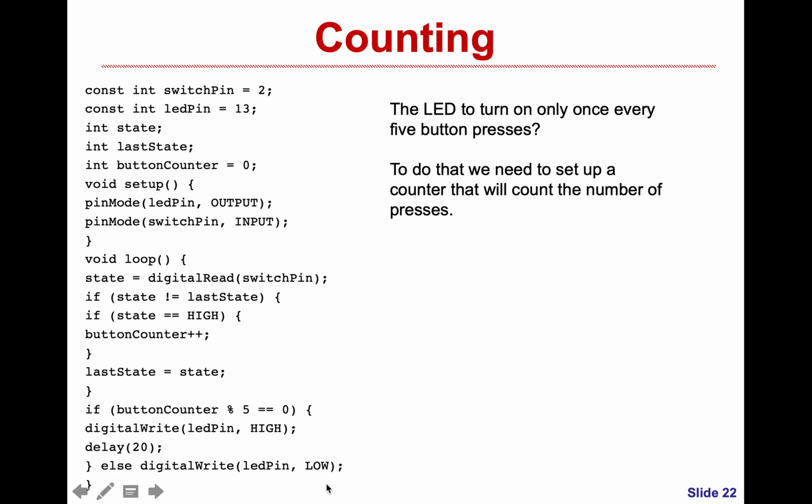So in this way, we will finish the digital input-output. Today in this lecture, we have covered the 14 digital input-output pins of the Arduino and the 6 analog inputs that can be used as digital inputs. We have seen how to specify that a pin is used as input or as output by using the pin mode function.